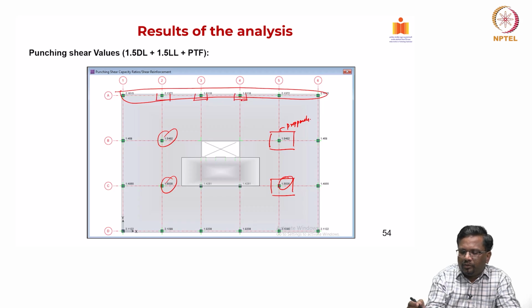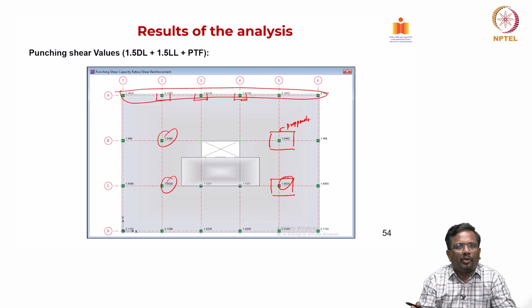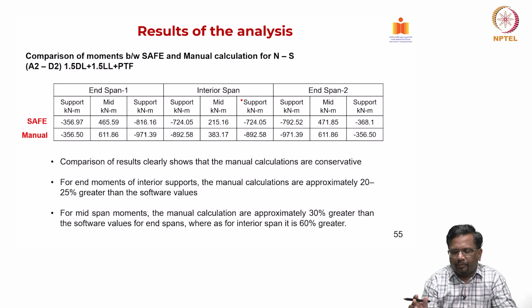Right. So, just to quickly show how the software values are being calculated, and punching shear particularly you have to be very careful, and you may end up providing some drop panel along with capital if required.